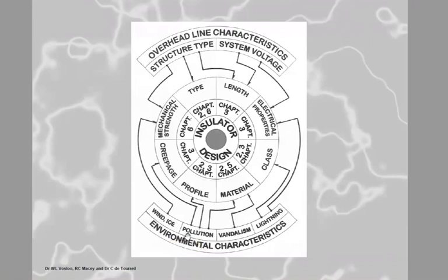And so pollution affects the creepage distance. The creepage distance is the distance from the live end all along the insulator surface, the shortest distance on the surface to earth. So they talk about the creepage distance. Okay? And then the profile of the insulator is what the sheds look like. Do they have an underrib? Or do they have a flat, open aerodynamic profile?